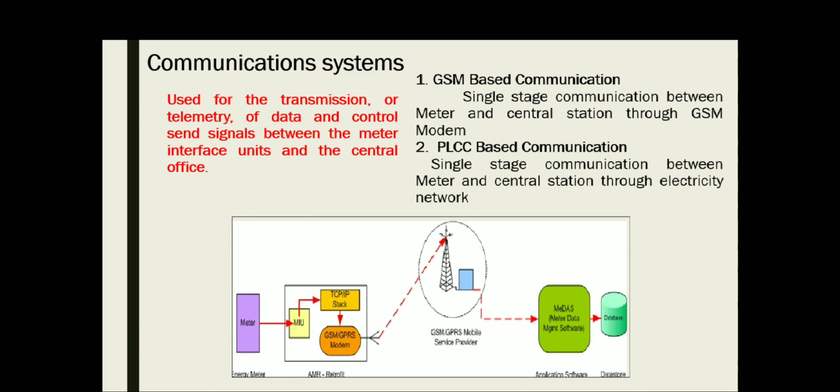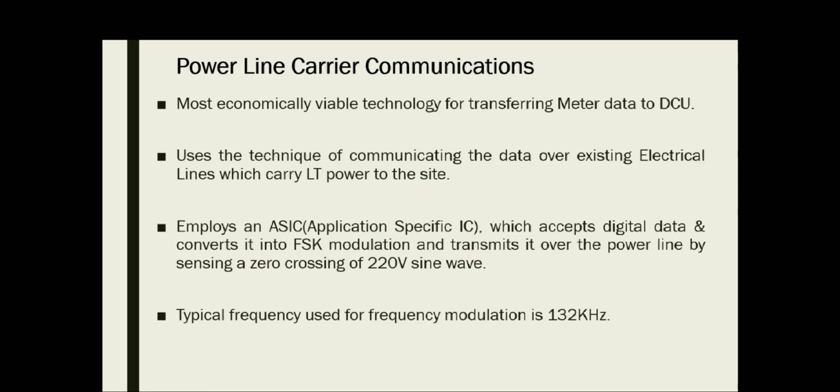So either GSM based communication or PLCC based communication. GSM based single stage communication between the meter and central station through a GSM modem is possible. Then PLCC, meaning power line carrier communication, is also used. Power line carrier communication is the most economically viable technology for transferring meter data to a data concentrator unit or DCU.